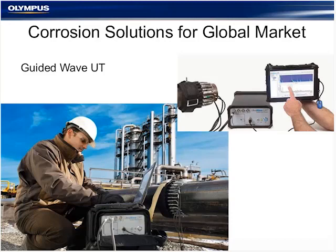And it has a pretty good reach as far as how far down the pipe, so to speak, it can see. Now, it is impacted by bends in the pipe, so the most ideal case would be a nice, long, straight pipe. But the advantage to this system is that the pipe can be buried. It might be hard to access the pipe, whether it be a vertical pipe that's going up the side of a silo or a building. It will also allow you to ignore any sort of coatings or buried pipes. So if the pipe is buried, it will give you a rough screening of how much corrosion might be present and how far down the length of the pipe.